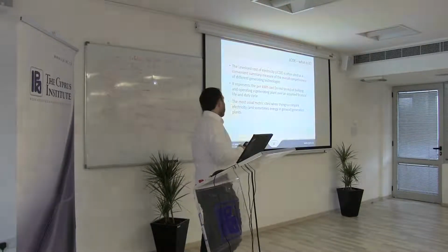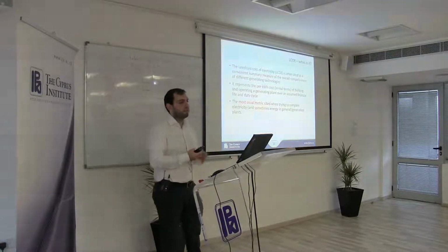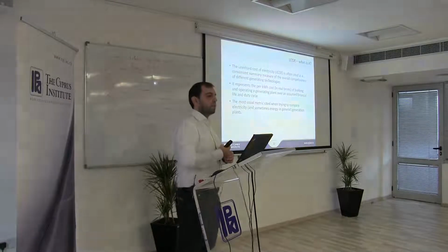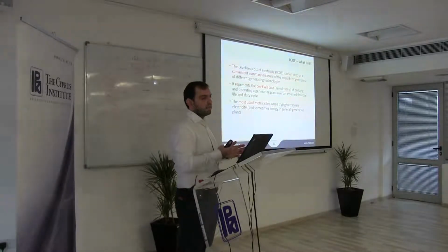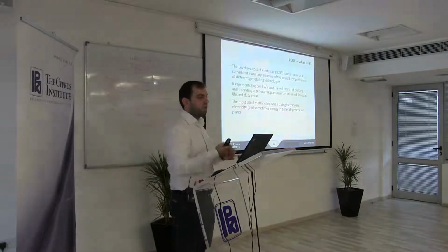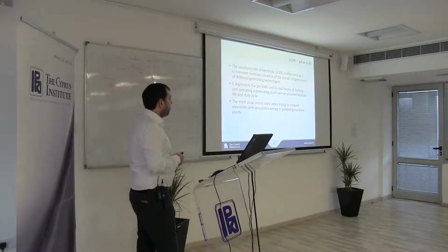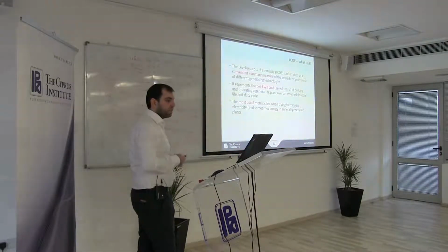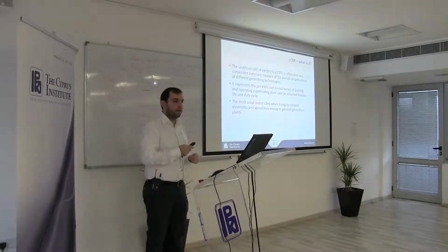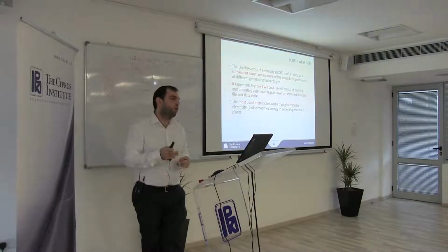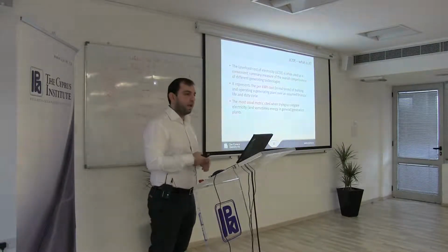So, for instance, for a coal power plant, we would have, let's say, a levelized cost of electricity somewhere between 5 and 8 cents per kilowatt hour, depending on the cost of fuel, of course. And we have these metrics for all different types of technologies, and I'll show some examples later on. This levelized cost of electricity is the most usual metric when trying to compare the attractiveness of electricity generation plants and sometimes other energy technologies.